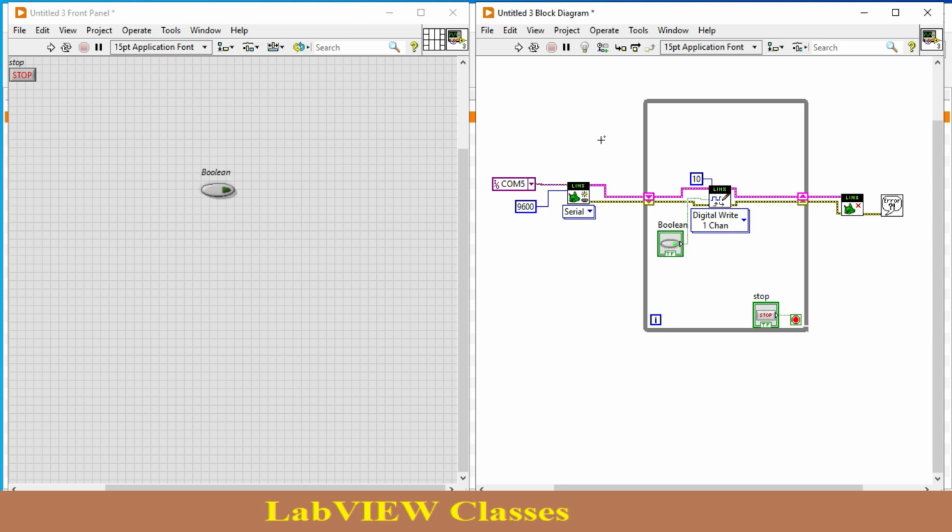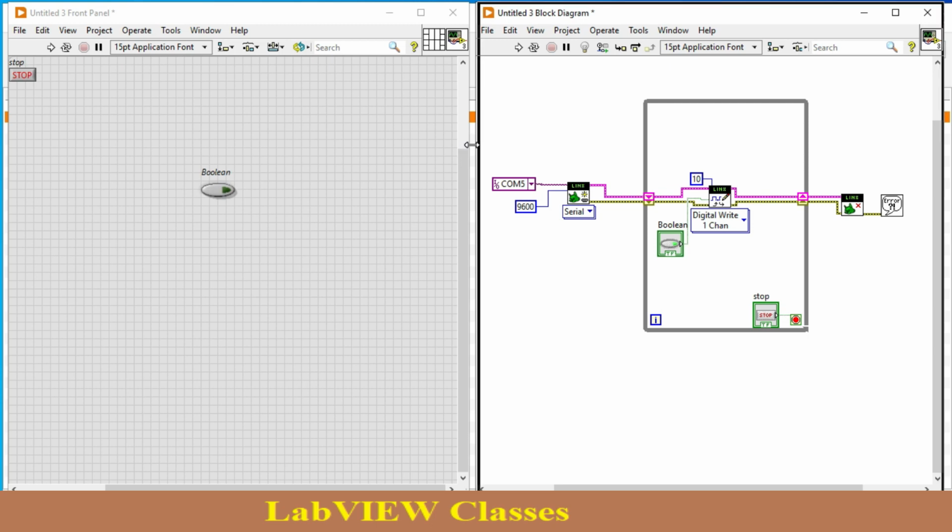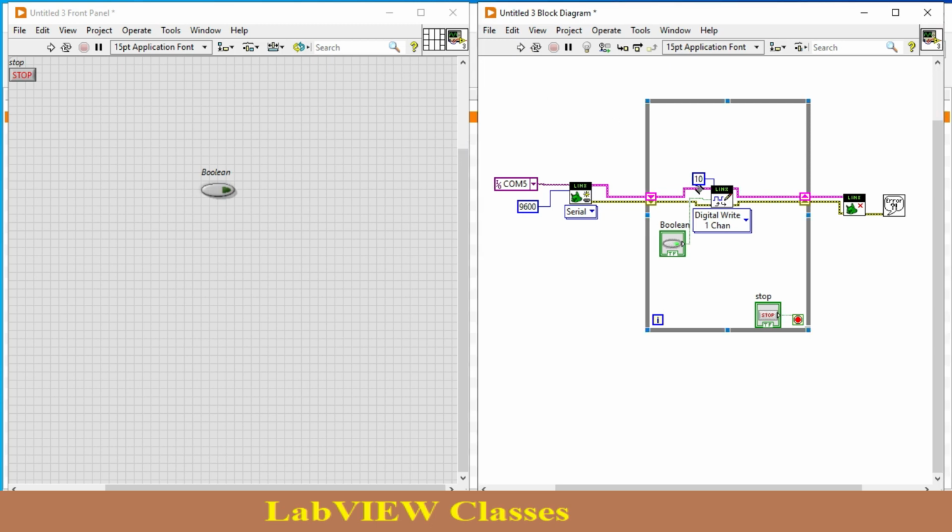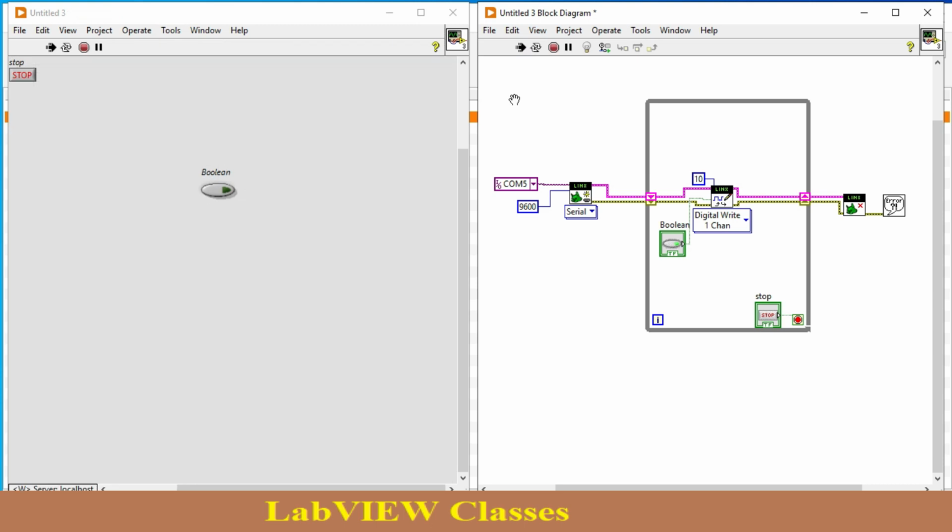Right now I'm just not connecting any resistance, but in the hardware part you just need a resistance, because this Arduino will provide you 5 volt and it will burn your LED. Right now I'm just connecting it without resistance. Okay, so again, right now I just change the pin number, as you see over here. So when I again hit on run button, it is not generating signal through 13 number pin. Right now it generates signal through pin number 10. So this is how you can generate signals using Arduino board. It is very simple.